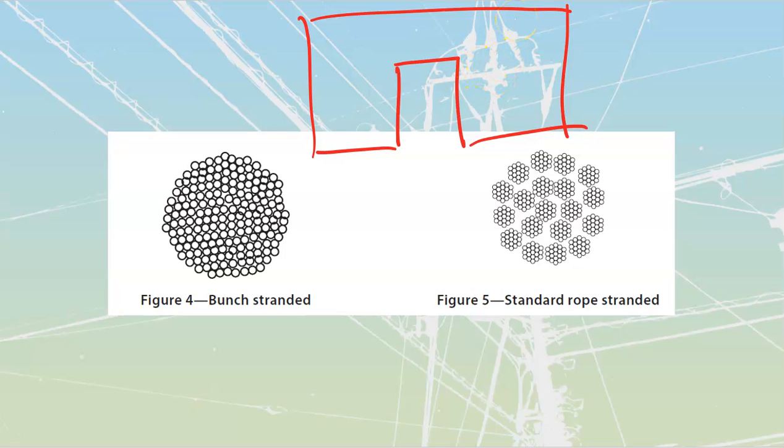So what you'll see in a lot of high voltage ones is on the hinge side of a door, there's going to be this flat braided conductor that's going to be bolted to the door and then bolted to the metal frame of the door itself. It's a poorly drawn frame. Let me see if I can do better than that. Bolted to the frame itself, and then all of this is going to be connected back to my main grounding component. Once again, specialized applications where we need to be very, very aware of our grounding, high voltage stations, but we will see it used for that.